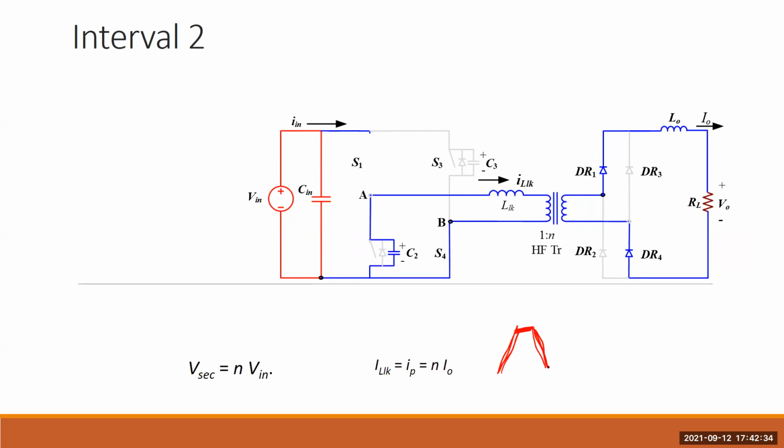I have seen some papers in which a DC capacitor is put in series with the winding. Many people put it there as a blocking capacitor, but just for safety reasons, in case there is a mismatch in the switching of S1, S4 and the switching of S2, S3. If there is a mismatch in the switching, or in the pulse width, then a DC component will appear. So they put in advance the blocking capacitor CB to avoid this.